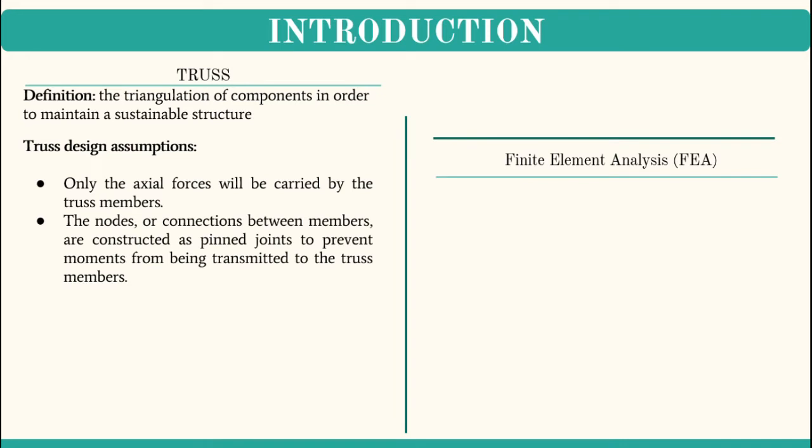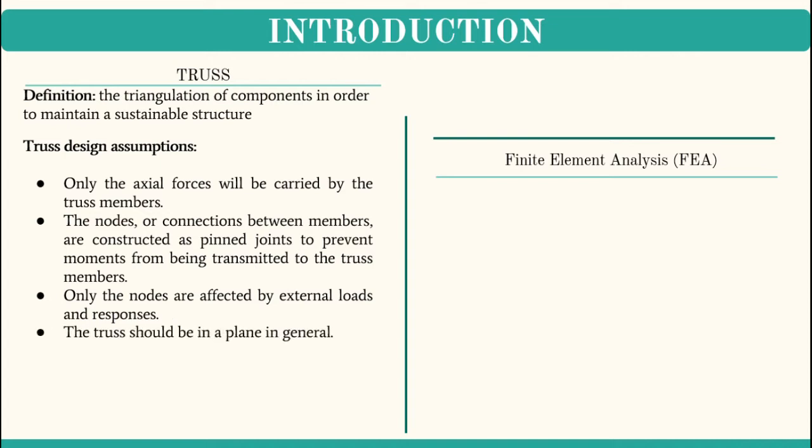Second, the nodes or connections between members are constructed as pin joints to prevent moments from being transmitted to the truss members. Third, only the nodes are affected by external loads and responses. Lastly, the truss should be in a plane in general.